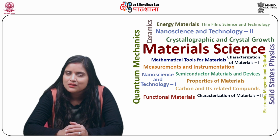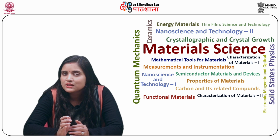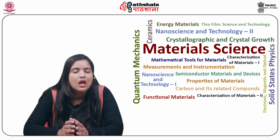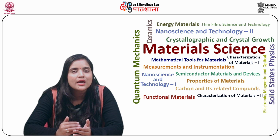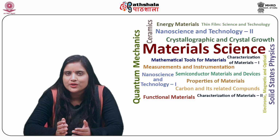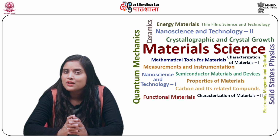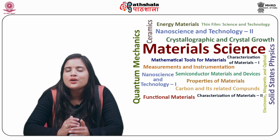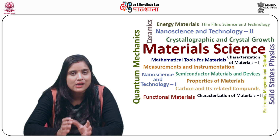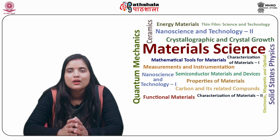High phosphorus coatings provide maximum resistance towards corrosion, and it is the industry standard where strong acid conditions are frequent, for example, oil drilling, coal mining, etc. However, these coatings suffer from poor solderability as they are only solderable for a brief time.